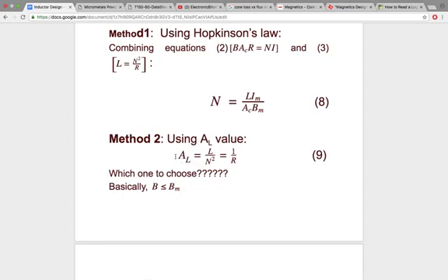But in this one, there is just inductance and number of turns. Nowhere are we talking about Bmax, and nowhere about Im. So how do we cross verify? If we use this AL formula, we have to cross verify that we are not going to enter into the saturation region. How do we do that?